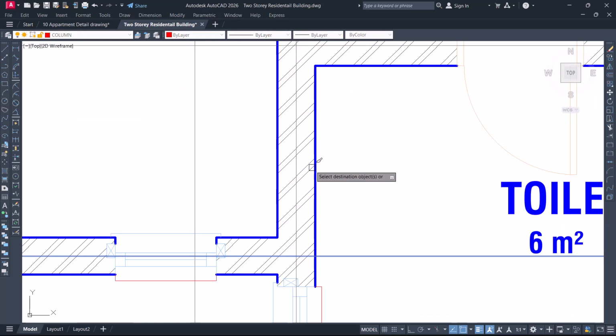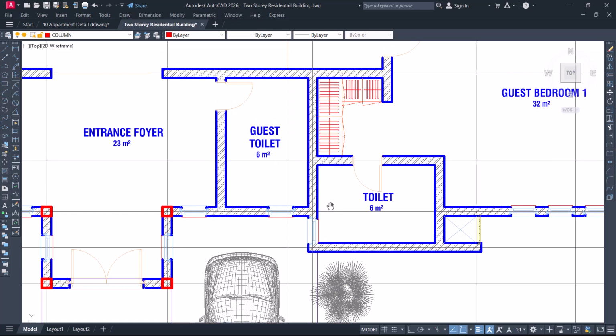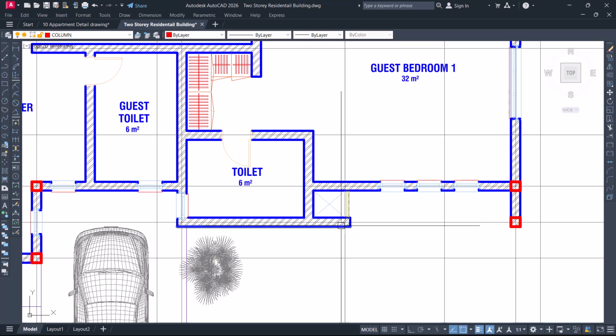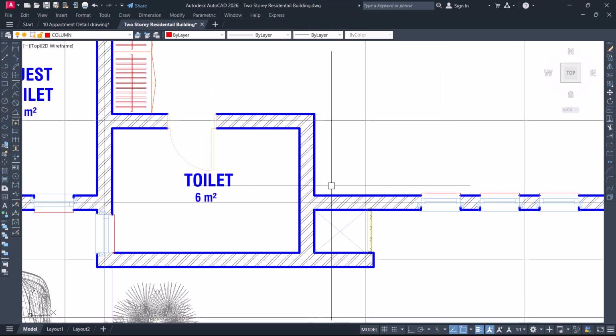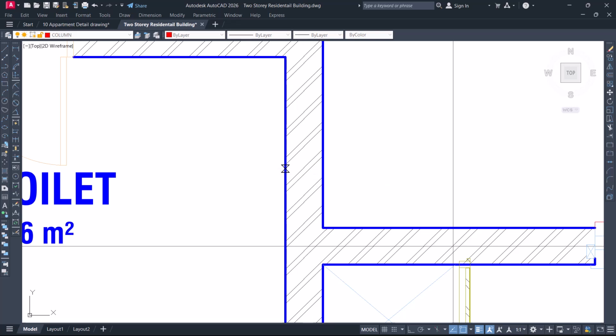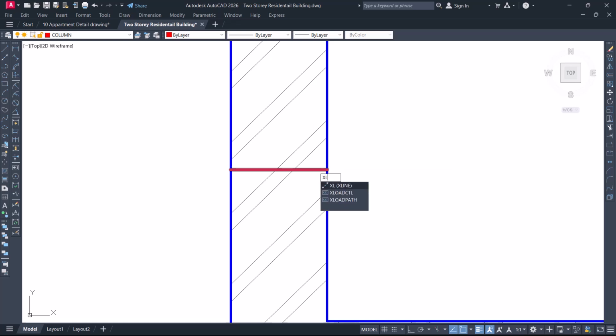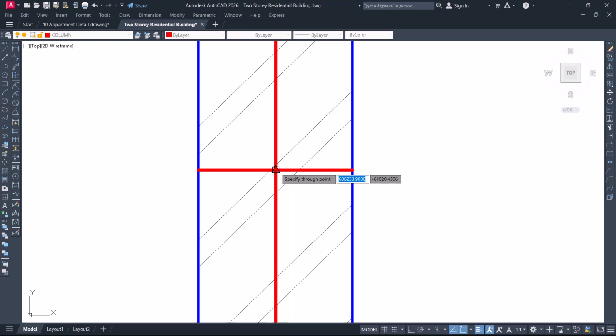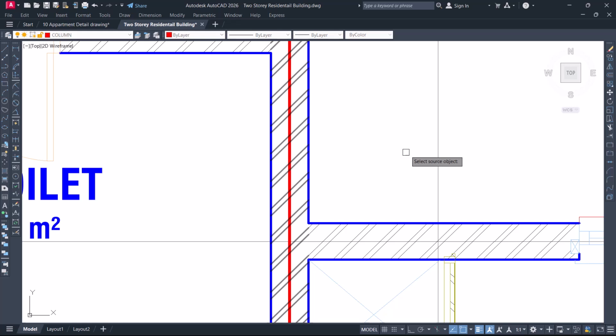Okay, and again, I also need, let me see, do I need a grid line here? Yeah, a grid line here. Okay, so I'll divide this again by 2. Now I can see why we need a structural grid line. Even if we took time to create our structural grid line, we would have known that we have to place column points around this area. Okay, so I'll come again now and create this here, remove this now, and again MA, enter, match this to this here.